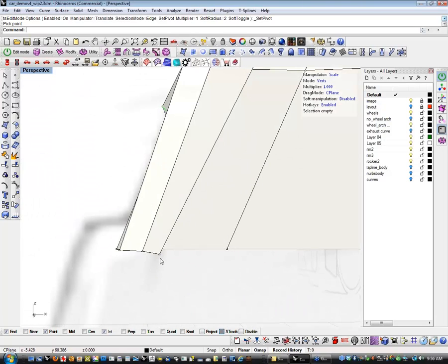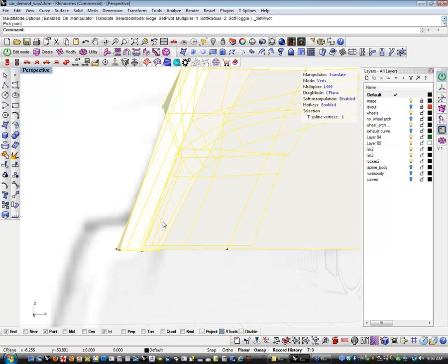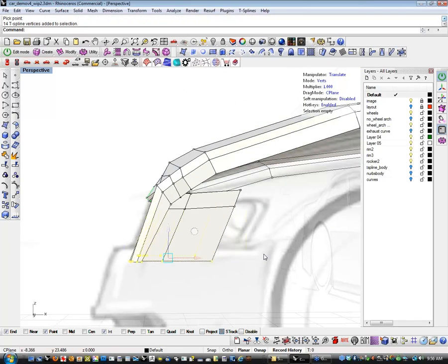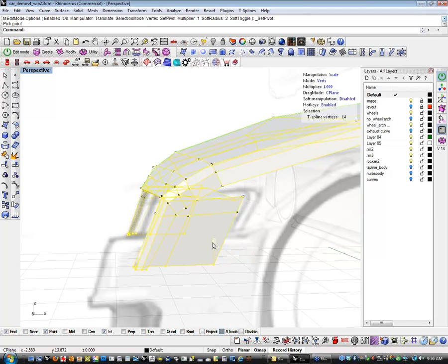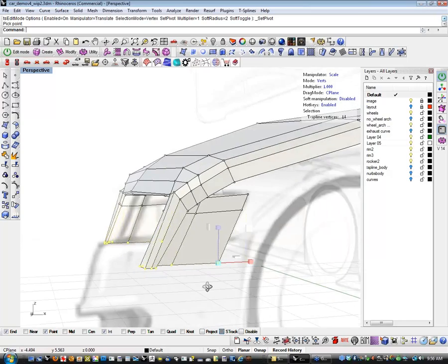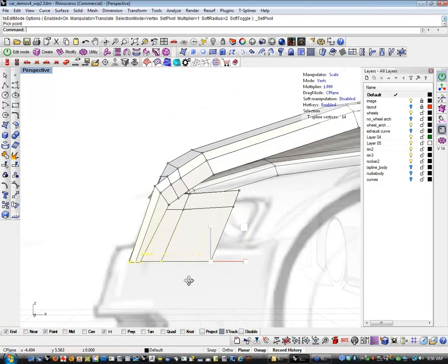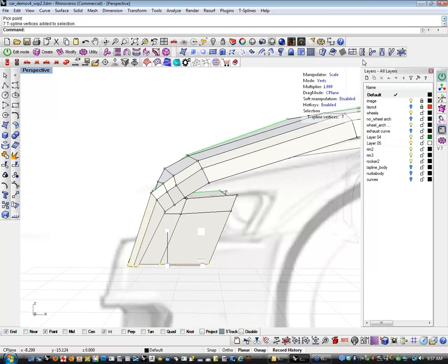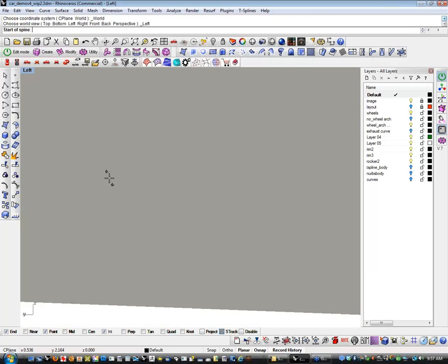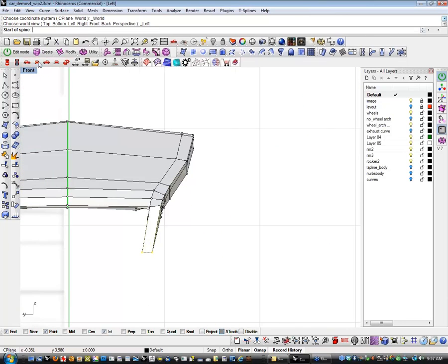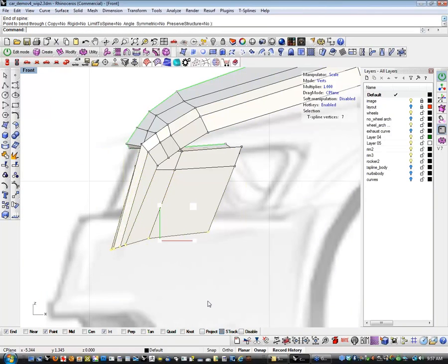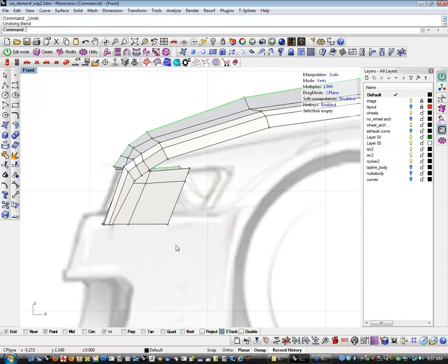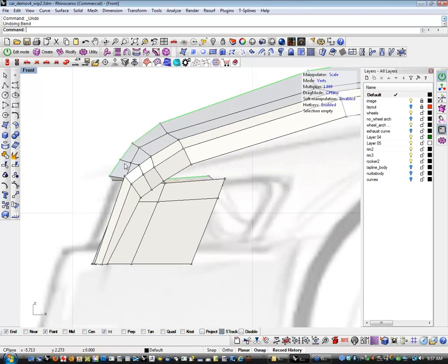And again, if any of you didn't see the first webinar, there's a great trick when you do stuff like this. If you scale this stuff, it's my favorite trick of all time, so I'm going to show it again. Straighten it out. If the thing gets screwy and you get it straightened out, then grab your points and use the bend tool. You can actually place points mathematically using the bend tool. No reason for me to do that here, but it's just such a great trick. I like to show it over and over and over and over again.